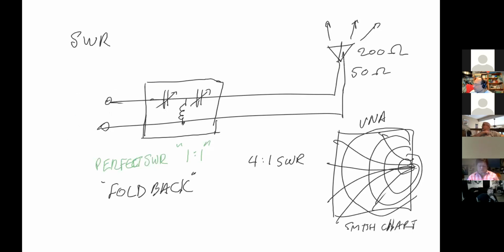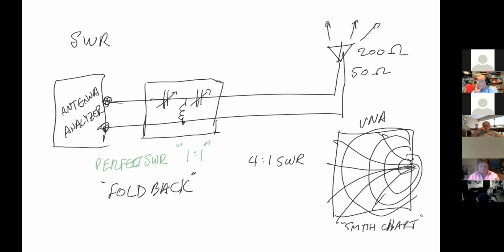And it has resistance circles and reactance curves. So that's kind of the advanced class. Never mind. But it's actually really useful to know. If you want to get a VNA, I will never tell anybody not to get a VNA. Now, the other thing to get is an antenna analyzer, which replaces your transmitter for a little bit and allows you to see what's happening in your antenna.